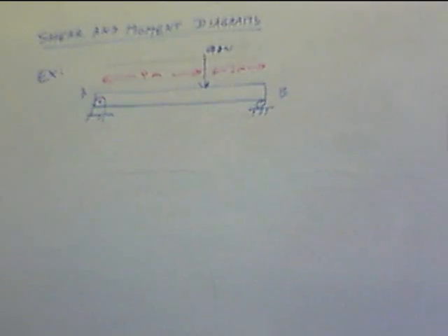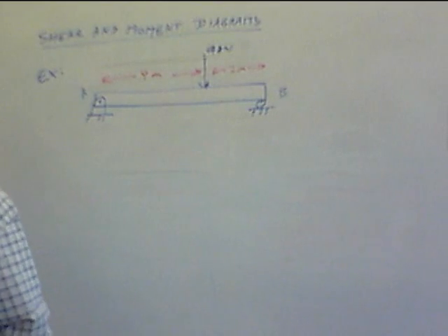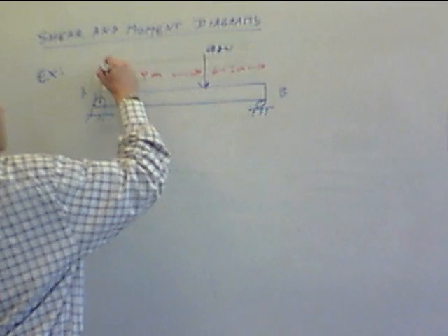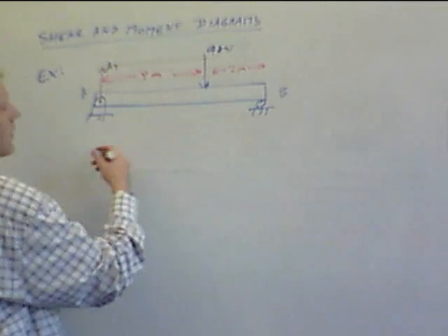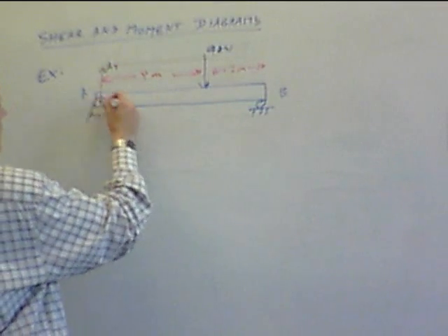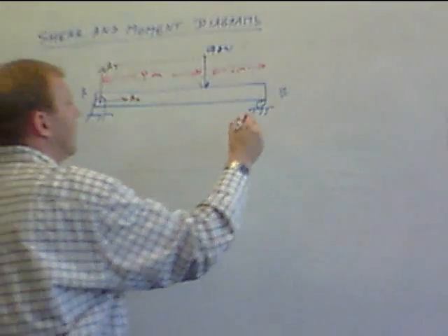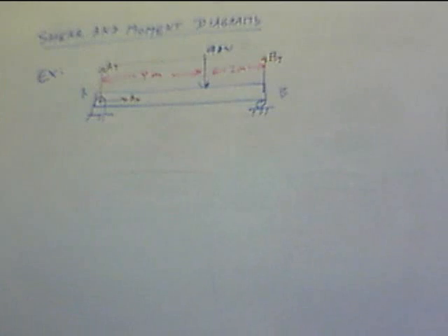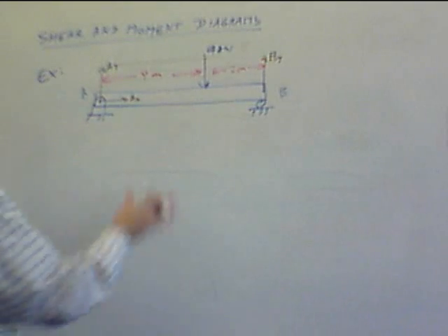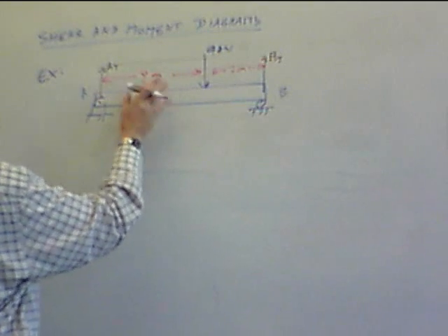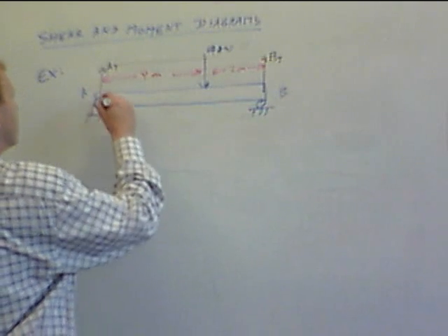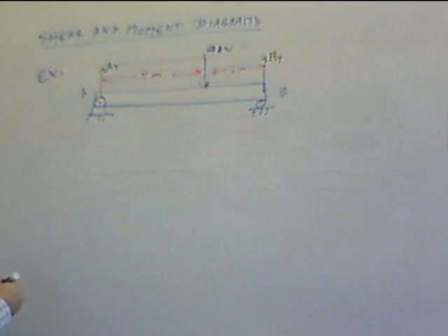Okay, we're going to have support forces here, as we always do. At the pin, we're going to have AY, and again, AX, I'll include it, we're going to end up dropping it in a moment. And BY. Okay, again, summation of forces in the X, AX equals 0, it comes right out. Same thing with finding support forces as we've done a dozen times before.